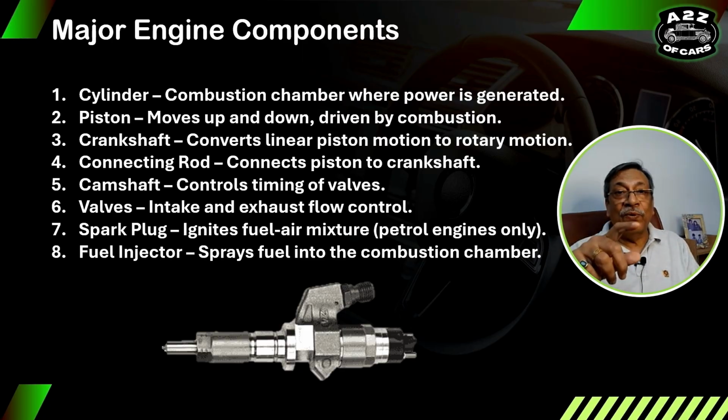Whereas in petrol, the injectors inject the fuel before the valve, on top of the valve, inside the intake manifold. What is the intake manifold? We will talk later. So there are fuel injectors in both petrol and diesel. In petrol, they inject the fuel outside the cylinder, whereas in diesel, they inject the fuel inside the cylinder.